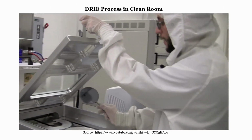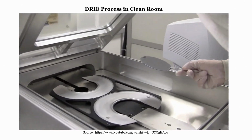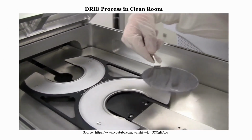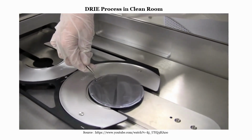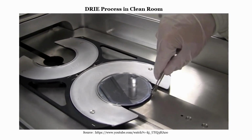As you will see, usually the wafers have a flat, and on the loading carousels we have a small line. Please align the flat with the line on the desired spot.